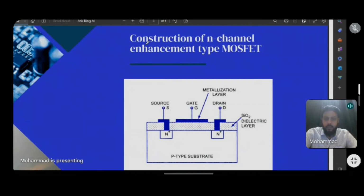For the construction of the N-channel enhancement type MOSFET, we need a base silicon, and that base silicon has to be doped using trivalent impurities so that we get a p-type substrate.